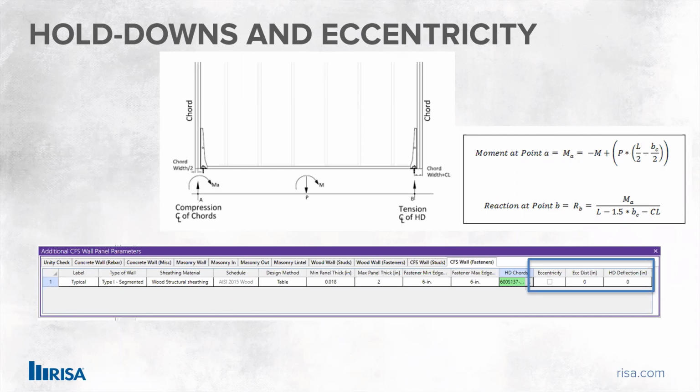So FEA, using the plate methodology, helps there, and we can actually show you the difference between what the plate's FEA deflection is versus what the hand calc method is, and you can use some adjusters to either stiffen up the wall. Typically it's the reverse of that, make it a little bit more soft so that you get more deflection like the hand calc represents. So I'll show you that in the results when we get there.